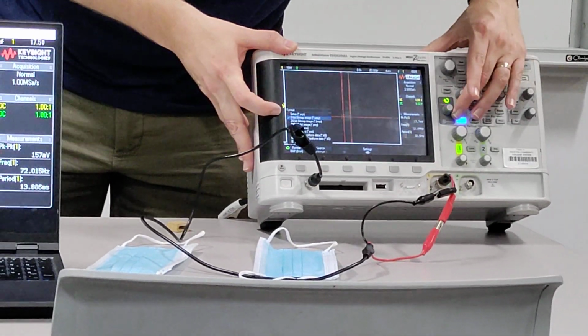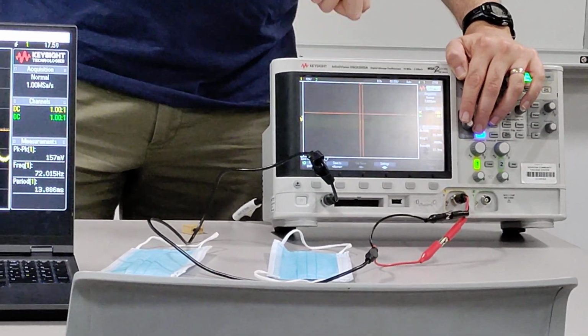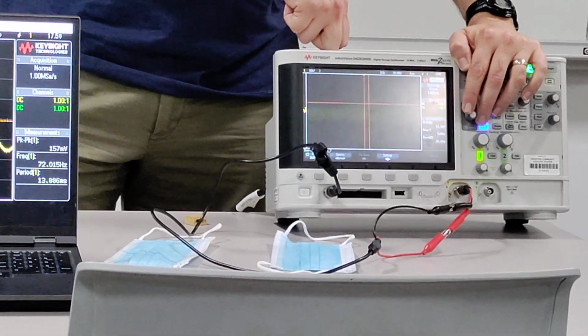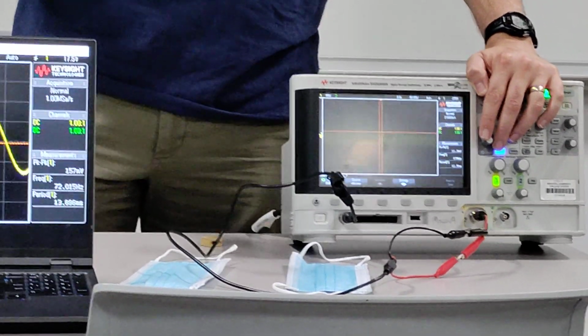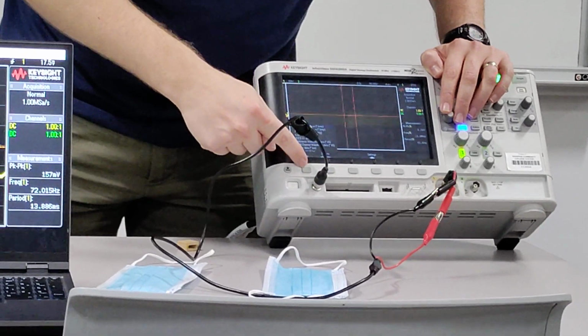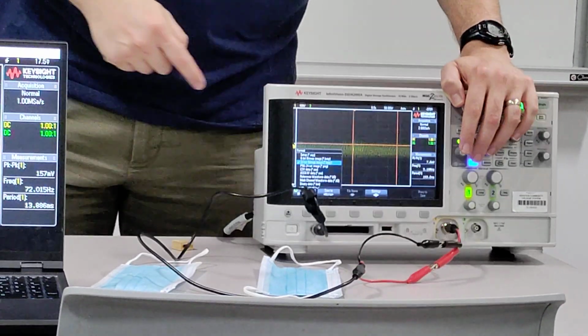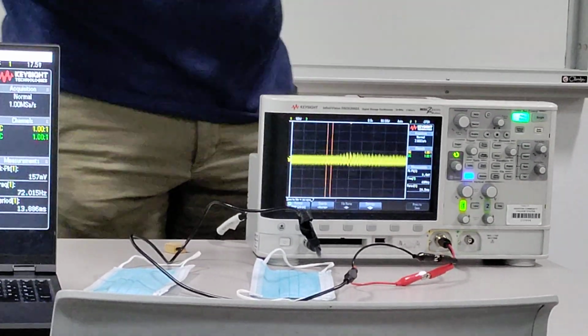The top option is a thing called setup. That is a text file. That's all the settings of this oscilloscope currently. So you can store that as well, so you can take it to another oscilloscope, set it up with the same settings to get the same information. But if you do that, you're going to be really upset later because it's, as I say, just a text file, says nothing about the waveform, will not help you.